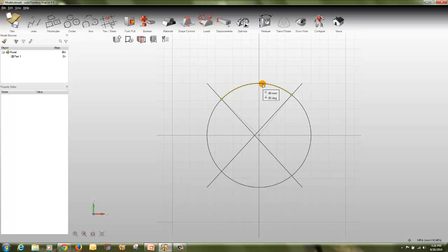So this has been broken. So you can remove it. Once you remove it, this is a different part. It will be a separate part from the actual geometry. So break will divide one component into two, but trim will remove that component or remove that line or remove that intersection. If you use trim, you can remove these sections like this.